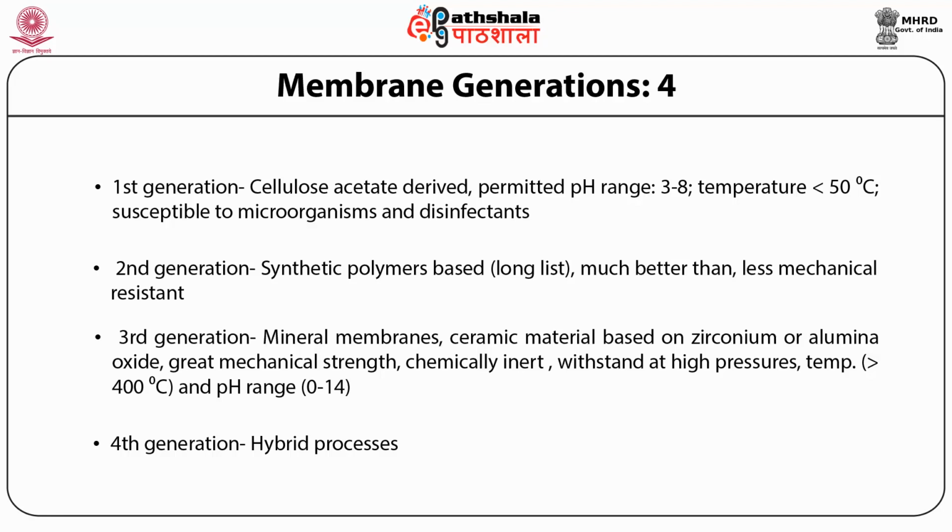Under the effect of an electric current, ions are transported from one solution to another through one or more semi-permeable porous membranes. Now we will discuss membranes in food processing. The availability of few food materials in their naturally pure form underlines the importance of different separation and purification processes in transforming food or feed substances into safe and directly consumable form.